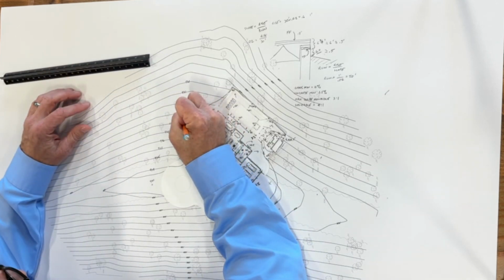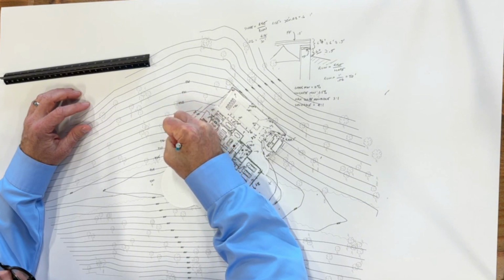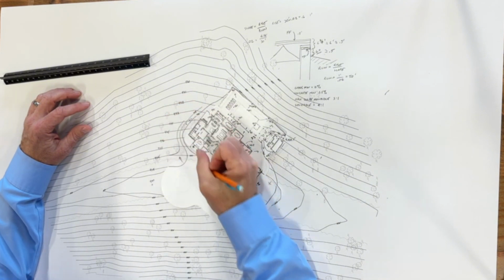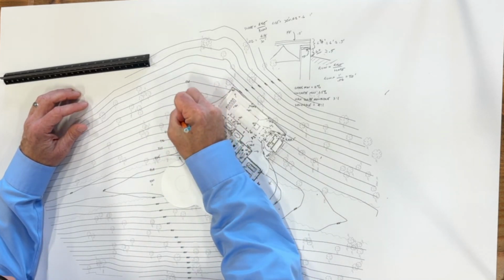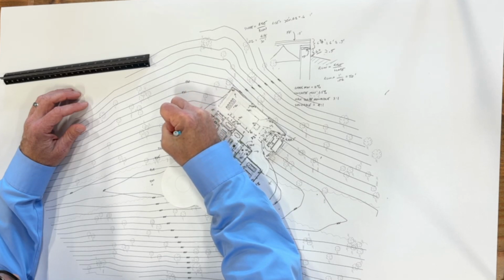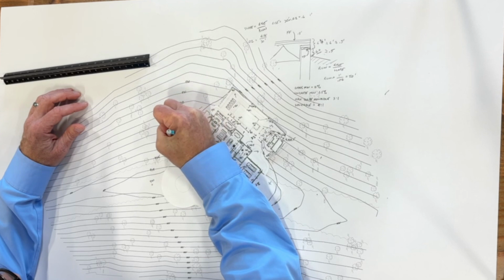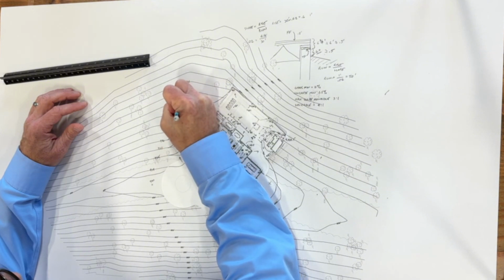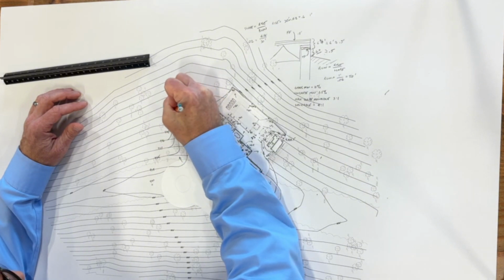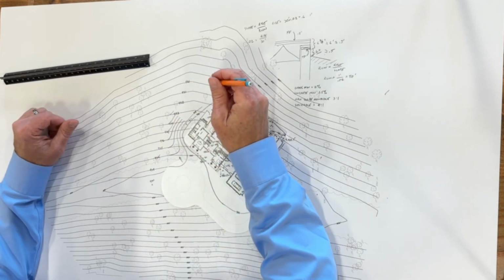There's a 938. And that is going to attach into this one. Again, you want it pulling away from the house, always. 937. Attach into this one. 936. Attach into this one. I'm just going to do it roughly for around 935. 934. And then here's the 933. So, and then that's how much dirt we'd have to move.